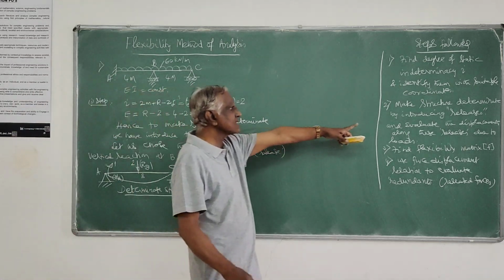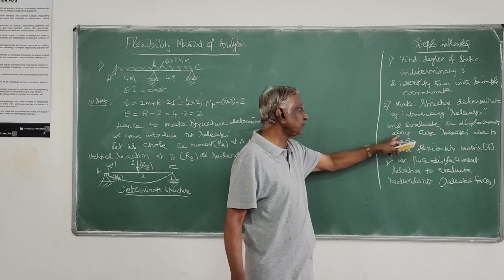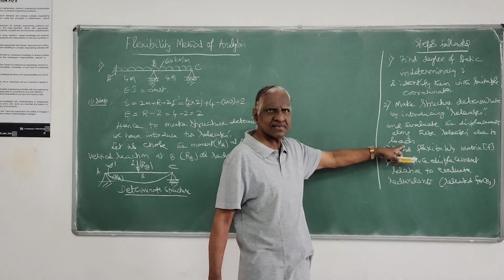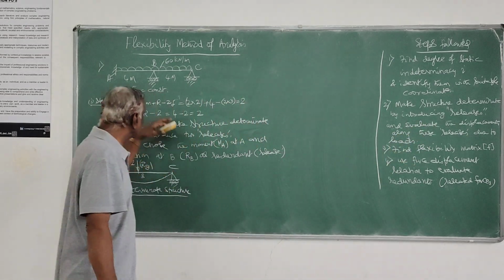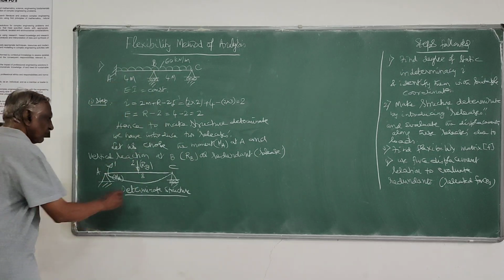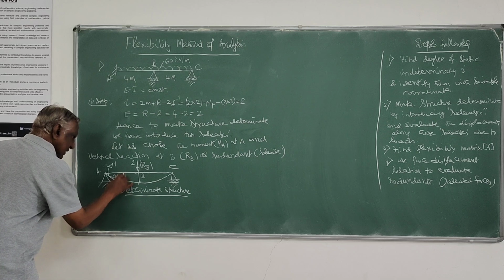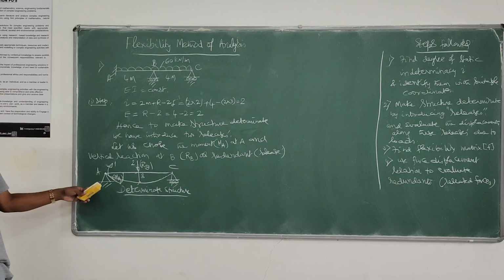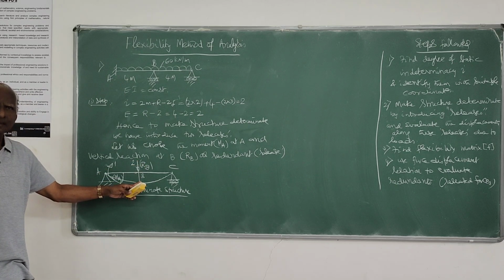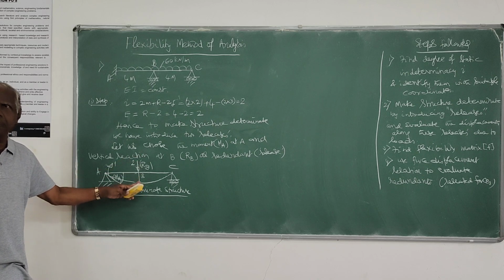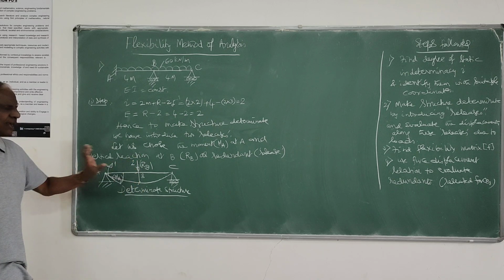That is your second step: evaluate the displacement along these releases due to the loads. That is here rotation, theta A, and here translation, YB, the deflection at B.